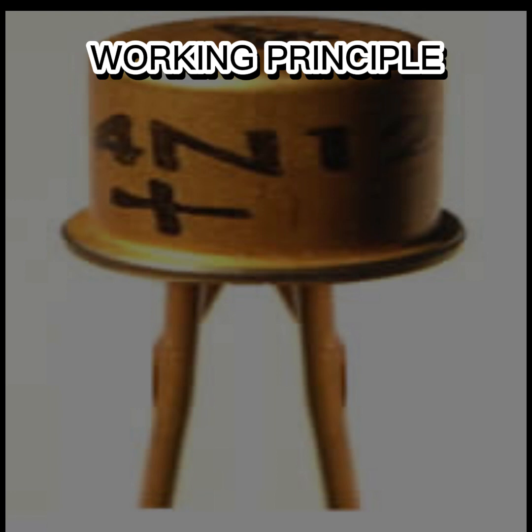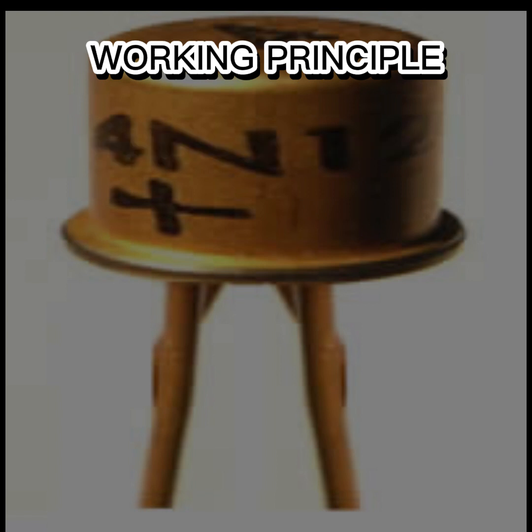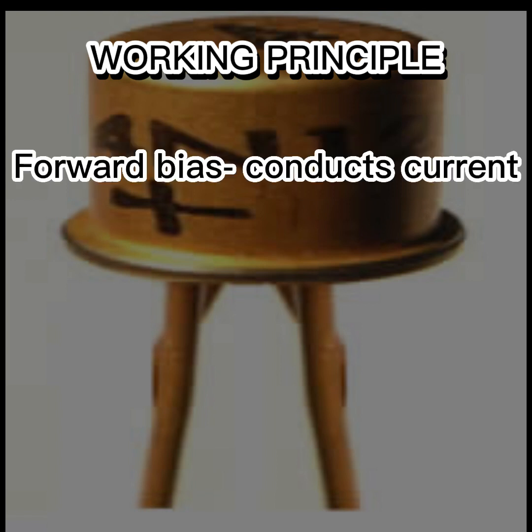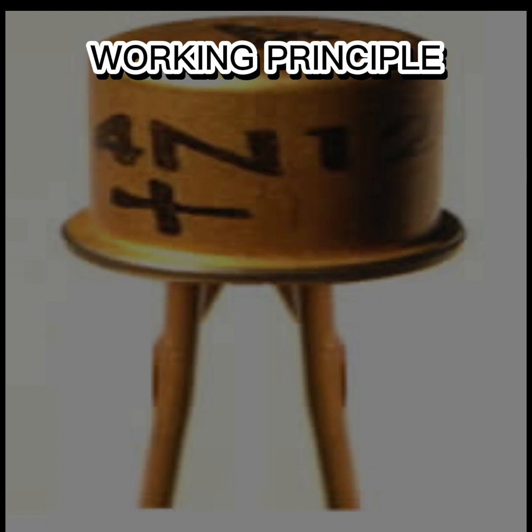Working principle of Shockley diode. The Shockley diode can be connected in forward bias and reverse bias. In forward bias, it conducts current if the applied voltage increases above the break-over voltage, while in reverse bias it blocks current. Let's explain these modes of operation.